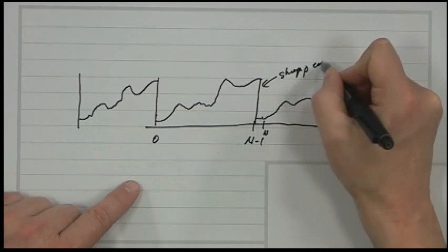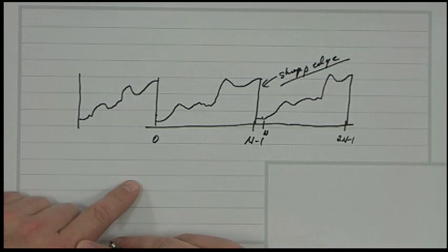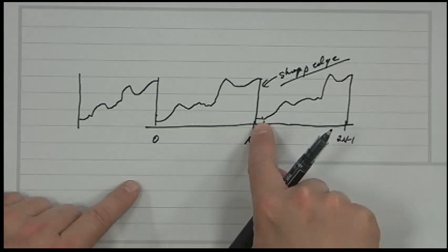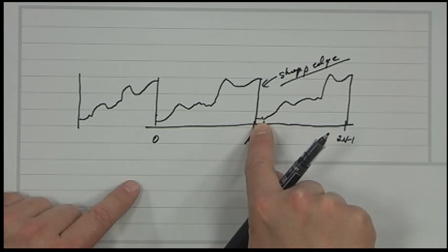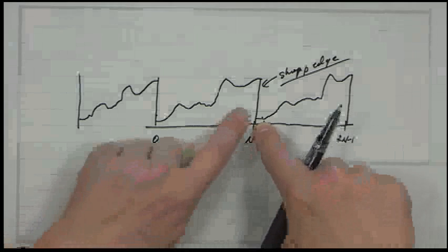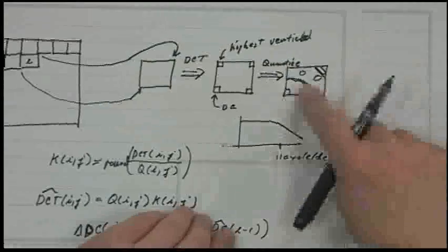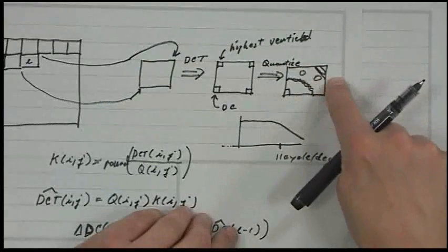Sharp edge. What's going to happen? What does the sharp edge do when I take the Fourier transform? Delta function. So when I take a Fourier transform of something with a sharp edge, what do I get? You're going to get a lot of high frequencies. And which was the part of the signal that was supposed to be 0? The high frequencies. So this is going to splatter all kinds of energy into the high frequencies. So if you do that, these things won't be 0 up here.